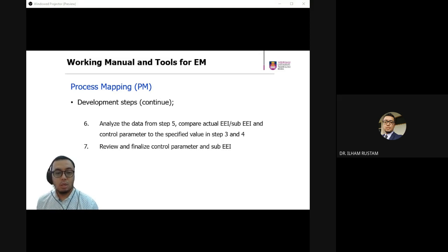Typically, when you're talking about kitchen, you don't need to have multimeter, data logger installed at the kitchen itself. Imagine this as in a big company, in a factory. Typically, when your bosses want you to do an energy efficiency program, your company will be big because you consume tons of energy, and then Suruhanjaya Tenaga issues you a warrant to come up with, remember, regulation 16. Once you consume more than 30 megawatt per 6 months consecutive, then you'll be served by Suruhanjaya Tenaga, and that means your company is big, consuming 30 megawatt per 6 months continuous, right? So it's justified if you have sub-processes that have their own data logger, not the whole TMD meter.